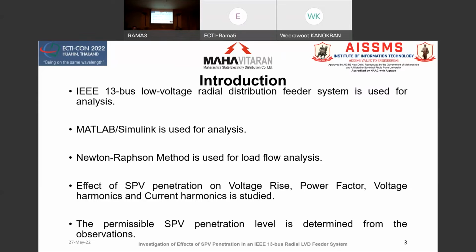these parameters in the MATLAB Simulink analysis. We have used the Newton-Raphson method for the load flow analysis. And the important thing which we have presented in this paper is the effect of SPV penetration on voltage rise, power factor, voltage harmonics, and current harmonics. And what we are trying to conclude is that the permissible SPV penetration level is determined from the observations. So with this, I would request my author, Mr. Shinde, to proceed with the implementation part. Thank you.